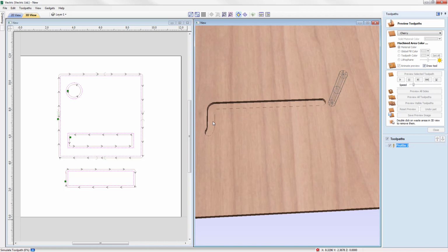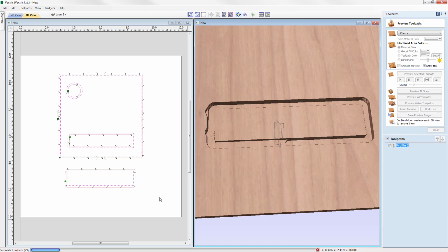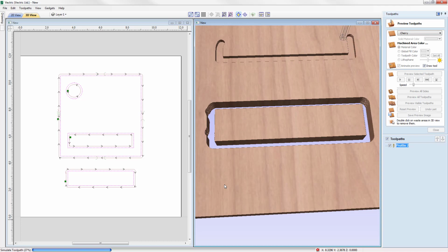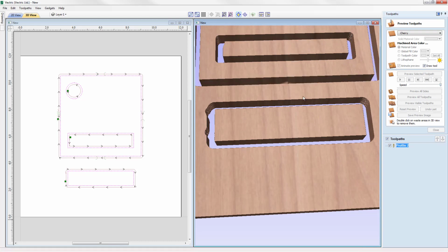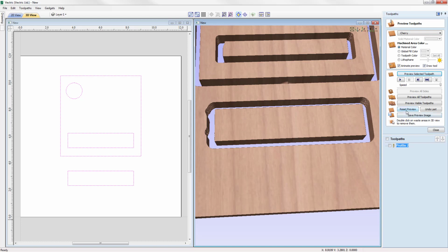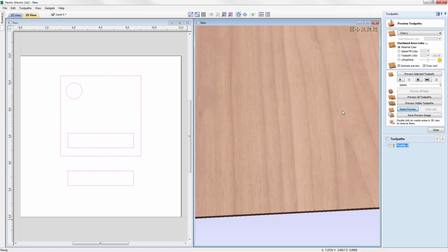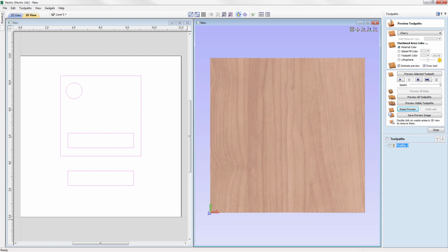We'll just slow it down so you can see the round edge going in and coming back out again, like so. And this is a more subtle curve into the cut path, which may give you a better finish overall, as using a straight lead with quite a sharp angle may cause the machine to make a sudden turn, which isn't going to give you as great a finish as may be achieved with the circular lead. So we'll just speed that up until that is complete, okay, and then we'll go ahead and reset that preview, and we'll put that back in Z.